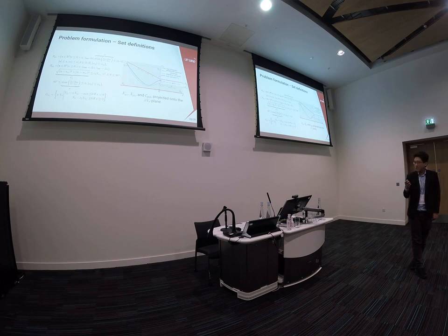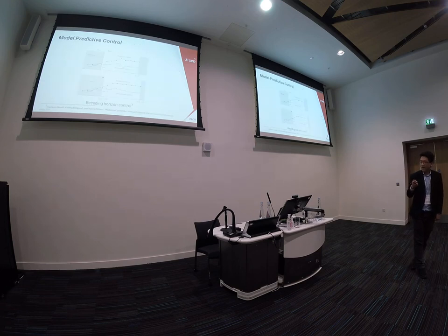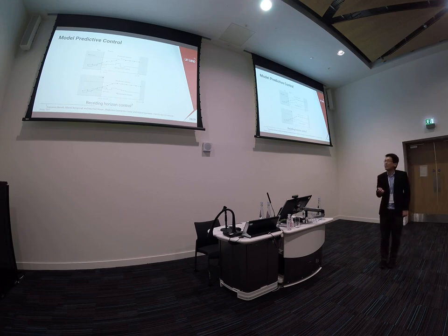Now this is the projection on the airspeed and X plane. So we want in the generation task, the constraint to be tighter than the one in the MPC task. The MPC is the part I will talk about next. Okay. Now for model predictive control, as you already know from my colleague Manuel. So at the time instance t, the controller tries to minimize the error between the state and the reference over a set of inputs, and then we only apply the first input, and then the procedure is repeated.